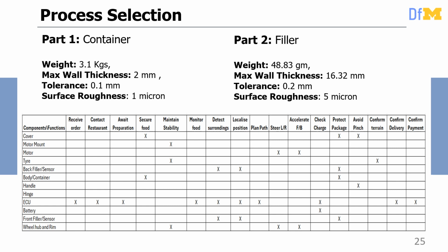Hello everyone, I'm Siddhartha and I'm going to talk about process selection. Process selection helps us in choosing a process which minimizes the cost of production by considering various specifications such as material, shape, mass, section thickness, tolerances, and the production batch size that we are planning for our product. We can choose the perfect process for our part. We take into account the process capability attributes and finalize the candidate processes. We use multiple charts to eliminate the processes that are incompatible at various stages.